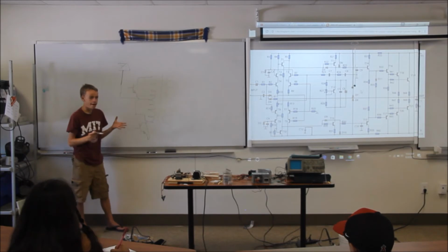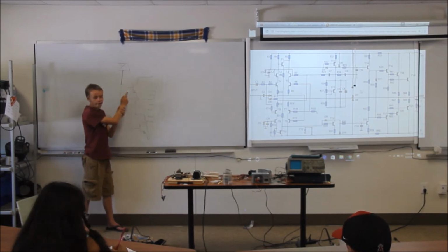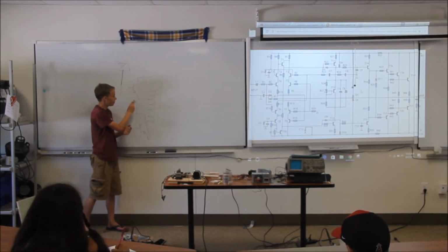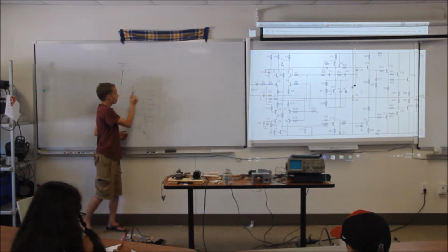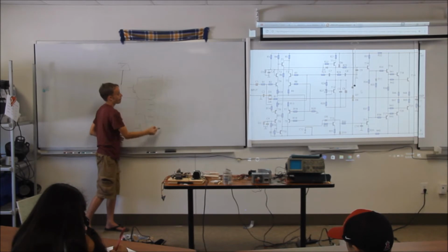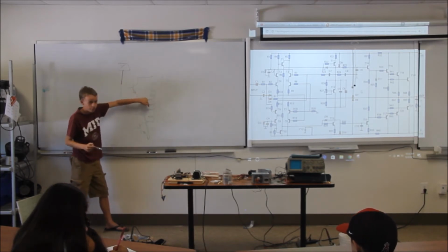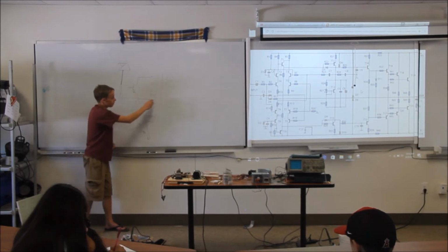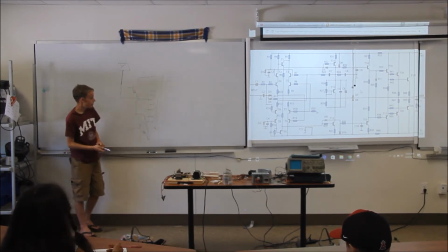And so we want to activate the transistors one at a time. We want this transistor to activate first, which means that the current will flow this side, and it will make the magnetic field going through the transformer go through this direction. And then we want this transistor to activate, making the current flow through this way, making the electricity in the transformer flow this direction.